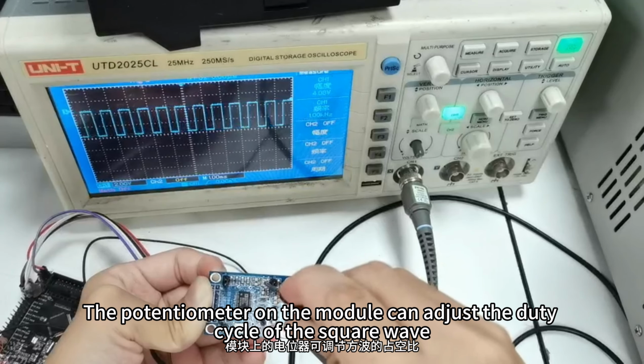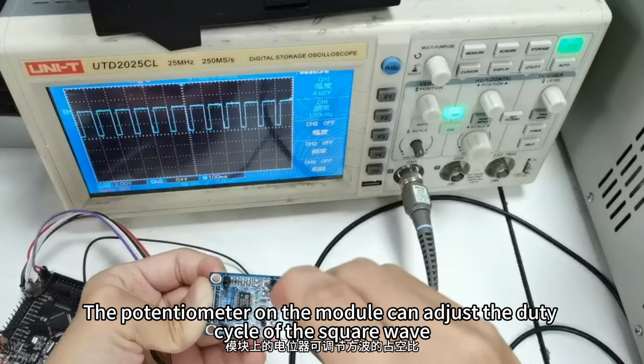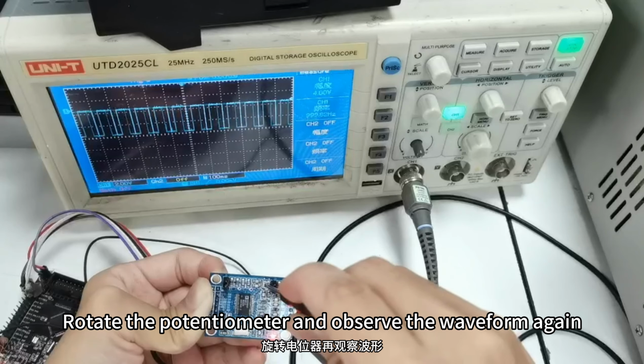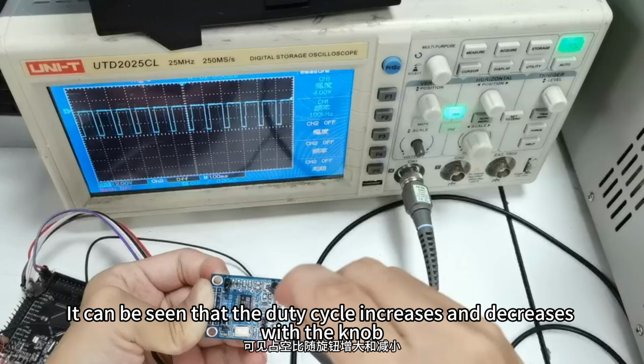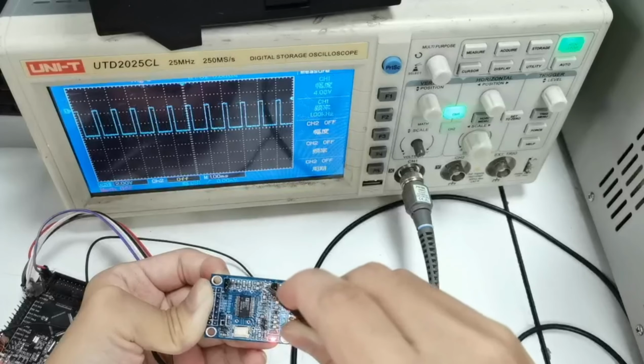The potentiometer on the module can adjust the duty cycle of the square wave. Rotate the potentiometer and observe the waveform again. It can be seen that the duty cycle increases and decreases with the knob. Module demo ends.